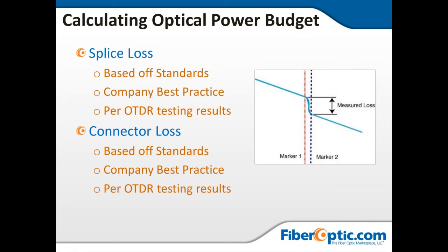Now, you heard me rattle off some splice losses. Well, they are based off of standards. And the most notable one was the TIA 568 commercial building standard, where a splice loss is 0.3. Now, typically, they don't use fusion splices, although it's becoming more common in campus networks. But it's based off the standards and does not differentiate between a fusion or a mechanical.